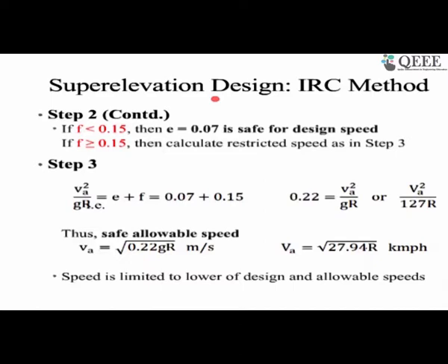The other thing is the ride quality. The bituminous pavement provides better ride quality than the concrete pavement, because of the resilient modulus, and concrete pavement is quite hard compared to bituminous pavement. Bituminous pavement is quite flexible and provides better ride quality.